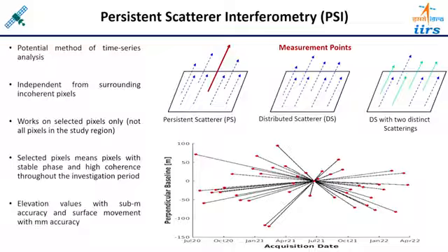Second thing is, since the accuracy of measurement of this technique is very high, it means these techniques are applicable over very, very slow deformation. It will not give the correct results over rapid or large scale or high deformation rates, or over the areas where the deformation rate is very high. Means the deformation is happening very rapidly up and down. So over those regions it will not give the correct answers.